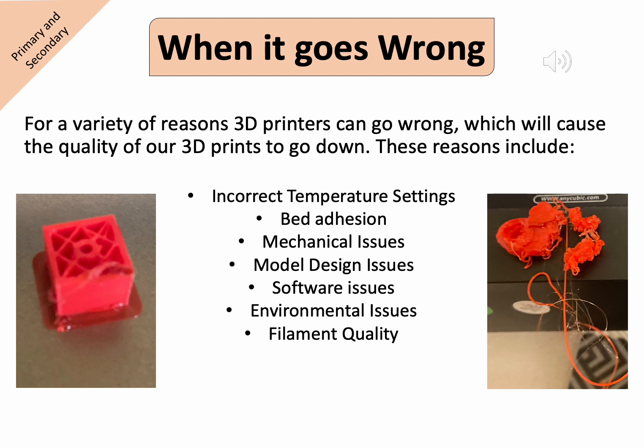We could also have environmental issues. If you're trying to 3D print in a room that's too cold, the print might cool too quickly. It could also be an environment that has lots of humidity, and this would affect the 3D print material. And as such, the quality of the filament can vary. Some cheaper filaments may have a reliability range of 0.5 mil, whereas good print filament would have a reliability of 0.03 mil.